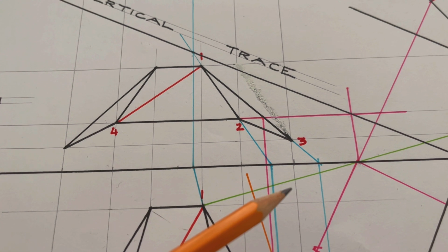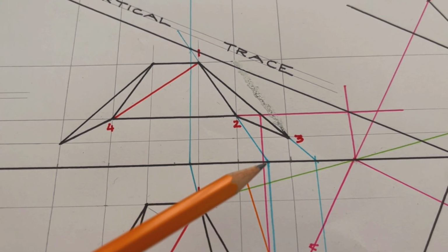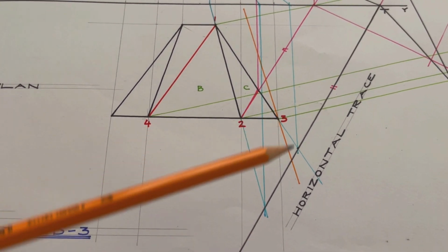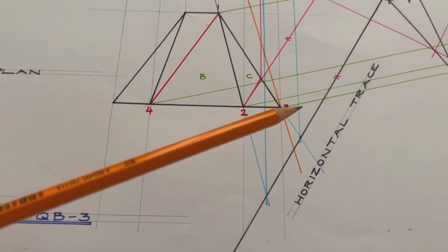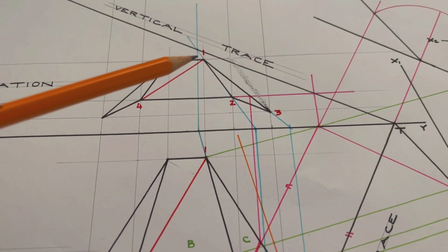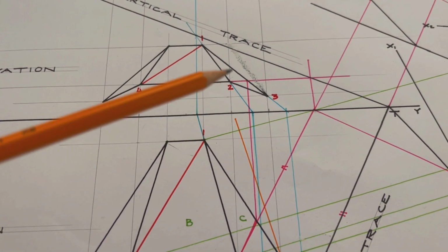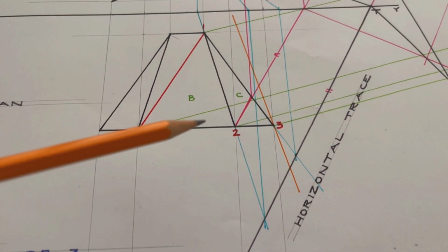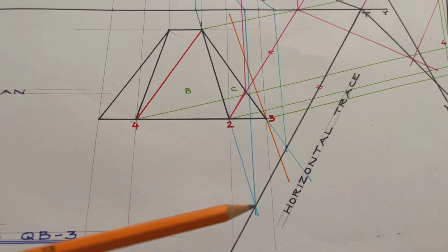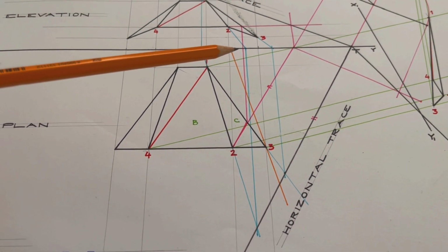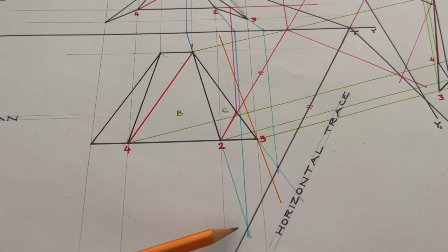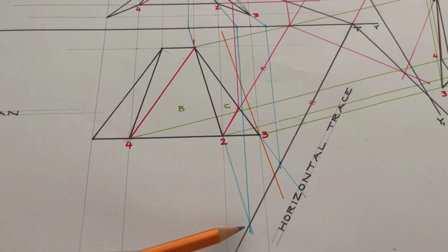Where are those points going to be in plan? Directly below it. So both of those points now, we bring them back down into plan. So the points we're looking for are on those lines somewhere. The exact point then, what did we do in elevation? We extended on 1, 2, and we extended on 1, 3. So we do that in plan. Extend on the line 1, 2, until it hits the line coming from that point there in elevation. Where the 2 of them cross, give you a point on the horizontal trace in plan.